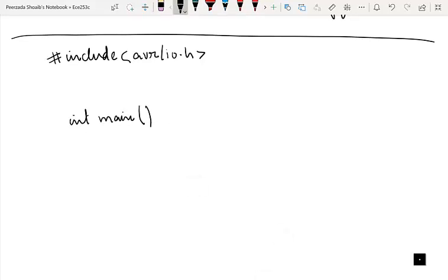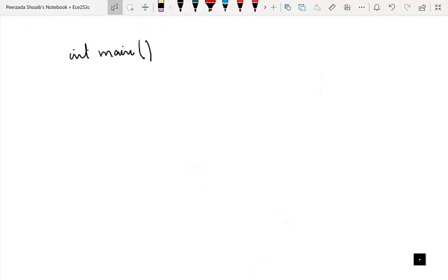Int main. So here goes my main program. So what's my main program? First of all, I have to configure the port. Which port? Port B, because I'm using port B as output port. And how do I configure port B as output port? There's a register associated with port B, that is the DDRB register. I write ones to that register. And you may be remembering how we write ones in an assembly language program using in and out statements. Here we simply assign that value. So I will simply write DDRB equal to 0.